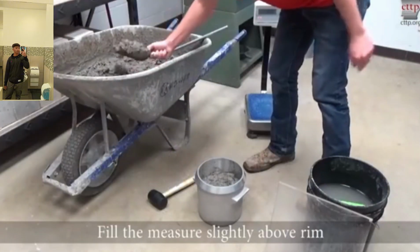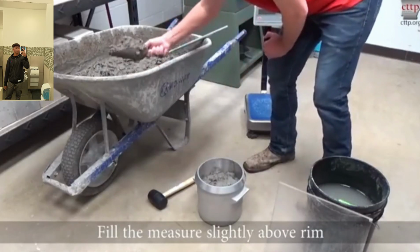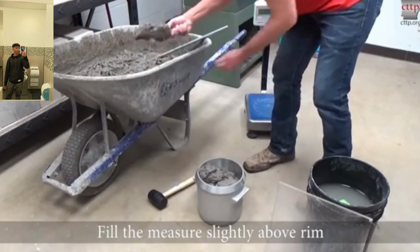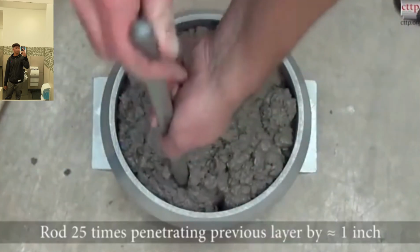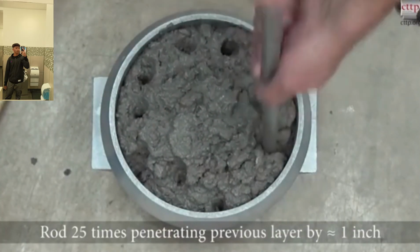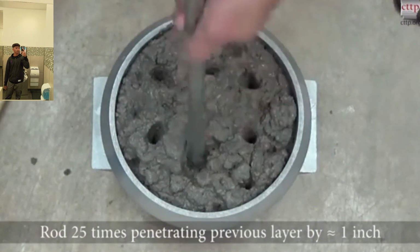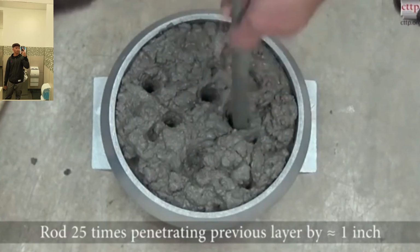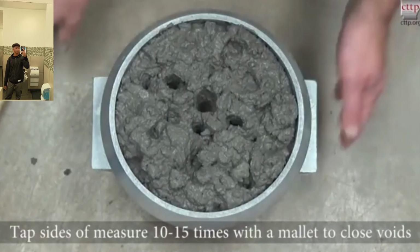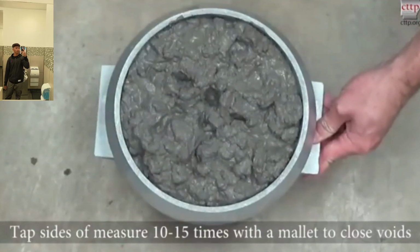Fill the measure slightly above the rim. Rod 25 times, penetrating the previous layer by 1 inch. Tap the sides of the measure 10 to 15 times with the mallet to close voids.